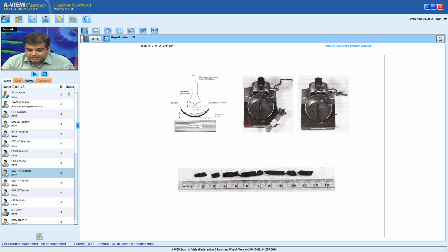So that's one original Casagrande apparatus, with this Casagrande tool. This Casagrande tool is to make a groove. I'm not sure if you can see this, the picture is quite dirty, but there is a groove. There's a part of soil, and in between the part there is a groove. This groove has been made by this elongated edge of the Casagrande tool. Remember, this Casagrande tool is like a fan-shaped tool.